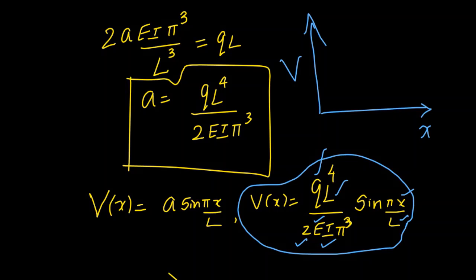Maybe you can use Excel or MATLAB, taking the deflection along the y-axis and the location of the beam along the x-axis, and you can plot your graph and find out that subdomain collocation method is actually superior to point collocation method. In the next class, we will see a method that is superior to subdomain collocation method, which actually gave birth to finite element analysis. In the next class, we are going to see Galerkin's weighted residual method.